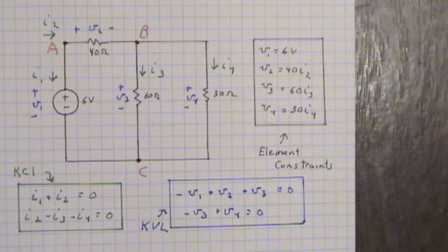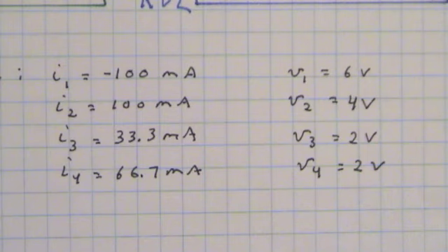Note that half the equations came from element constraints, i.e. what components we picked out of the components bin, and the other half come from connection constraints, how we connected them. These 8 equations can be solved by whatever linear algebra methods we like to use, but these are the numerical results. We'll leave that as an exercise.